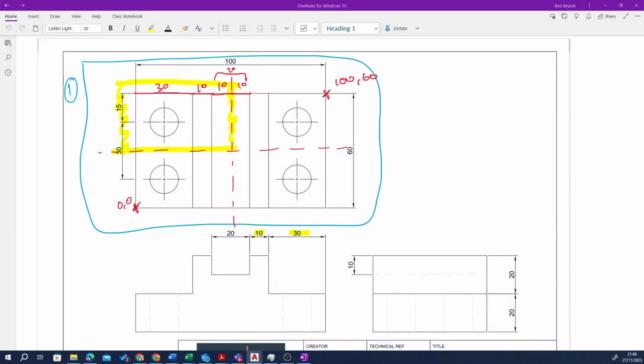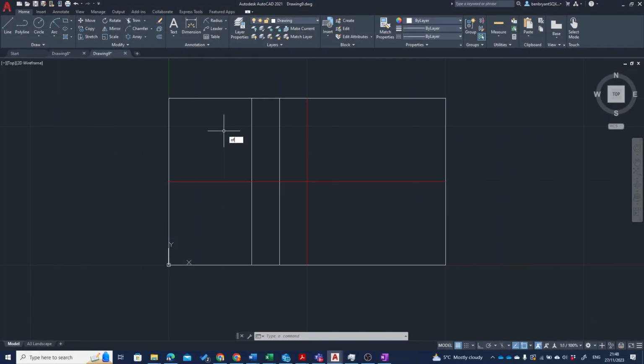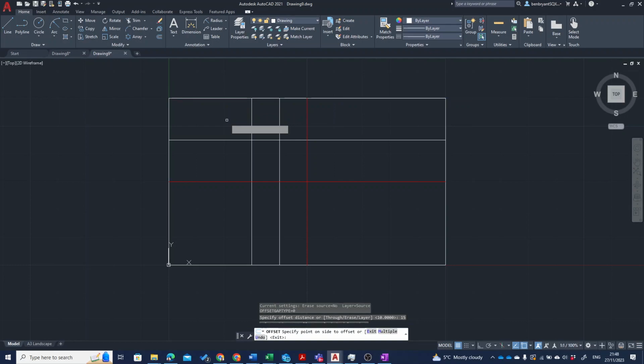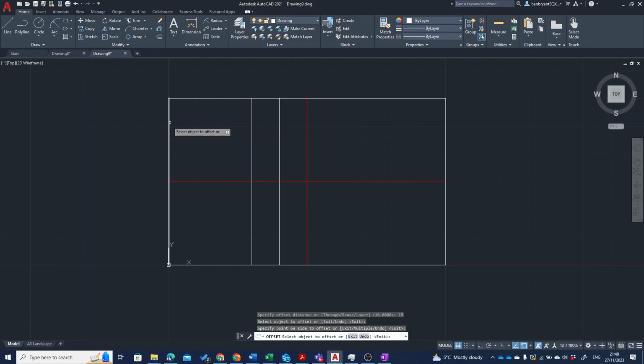Next, you'll notice on the screen that the circle drops down from this red line to the center point. It drops down 15. So do another offset here, 15 down, which is going to form the base of my circle, and it also forms 15 within the 30. So because I've picked up 2 lines on the drawing layer, what I'm actually going to do is highlight both of these lines.